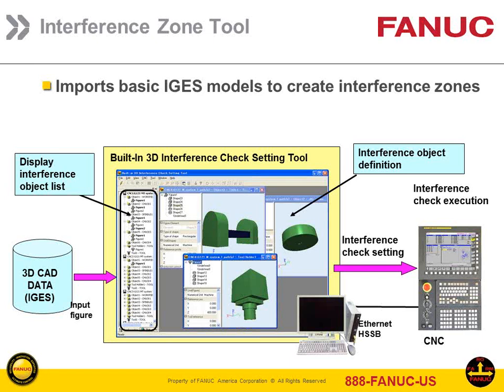So again, I want to emphasize that this is very important when you do 5-axis machining, because like I said before, it's not like throwing a part up in a vise. You're going to have special fixturing. You need to be able to get all the way around the part, so it's important that you have some means of being able to machine all the way around the part.